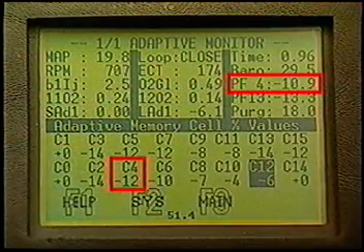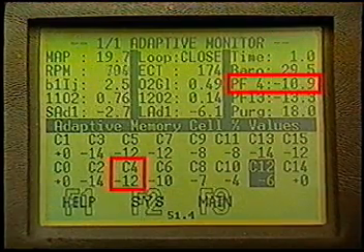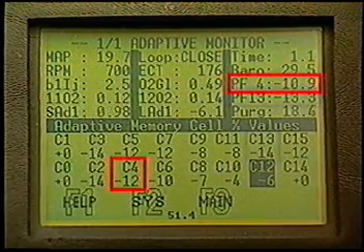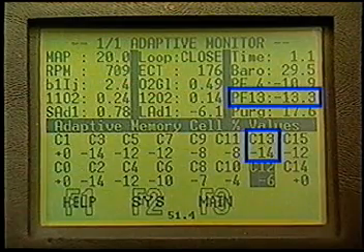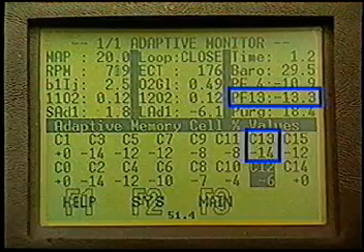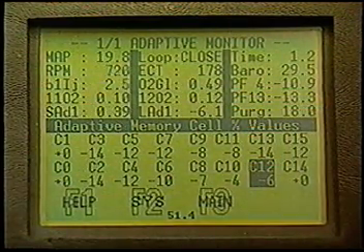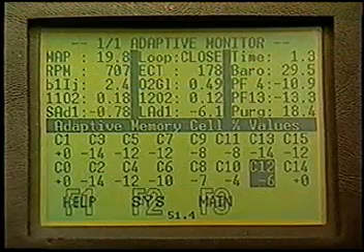Leak detection is just one aspect of the evaporative emissions monitor. The system also uses a separate monitor to test purge flow. It does this in two stages. In stage 1, the PCM compares short-term fuel trim of purge cells to purge-free cells. If there's a significant difference between cells, the PCM assumes that purge is operating and the monitor passes. However, if the difference is not significant, the monitor will move on to stage 2.